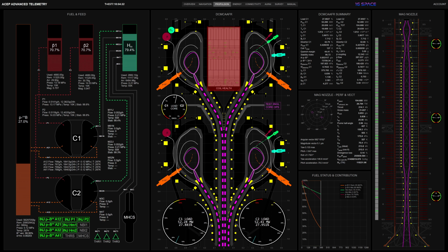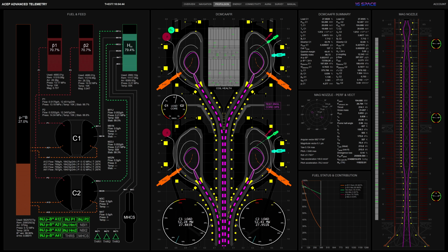The coil health matrix represents continuous diagnostic sampling of the magnetic confinement system at the level of individual coils. Each coil is periodically and pseudo-randomly evaluated across 3 dimensions: magnetic field stability, thermal margin to quench, and current balance relative to commanded load. This distributed sampling strategy avoids correlated stress artifacts and provides early detection of localized degradation before it propagates into global confinement loss or stability constraints.